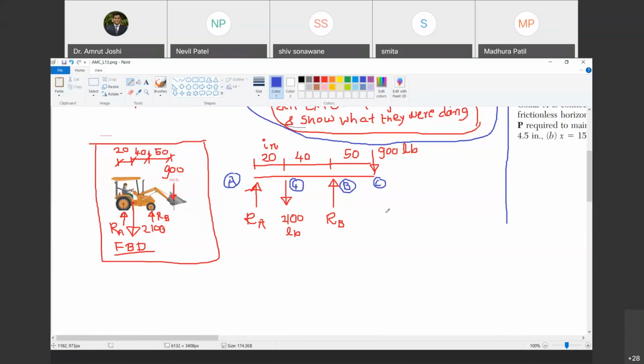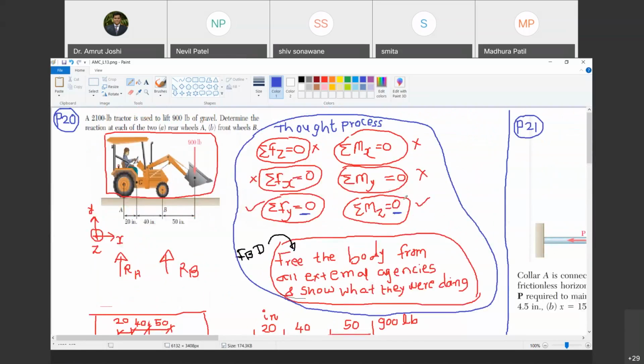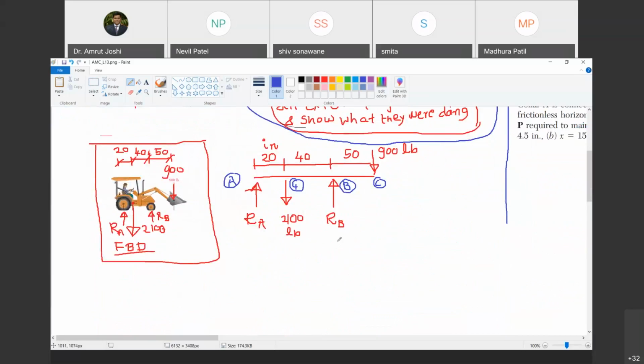while we know that there are two equations and two unknowns, it is always better to choose the equation to be used first wisely. Think a little before deciding which equation we are going to use first. That simplifies the problem to a larger extent. How? Now look, I have to take summation of moments of all the forces about z axis. Natural question that I am going to ask is, z axis passing through which point?